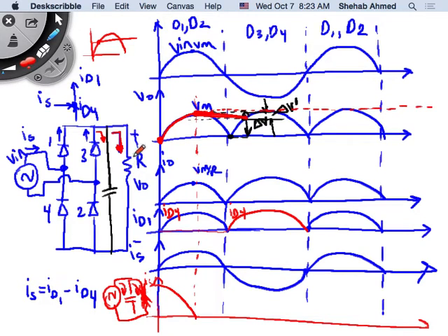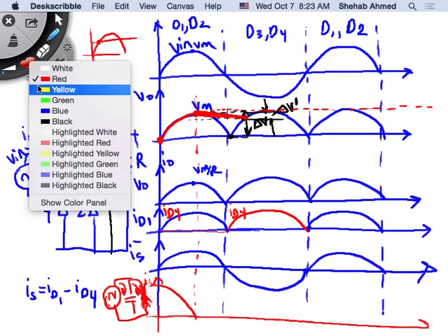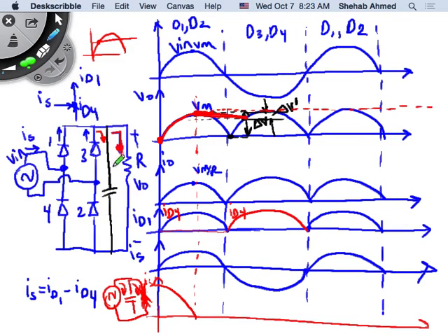So the real case, we will have a resistor connected. If the resistor is connected, what's going to happen? At this point here, we said the supply voltage starts falling. That's fine. And the capacitor voltage will also start falling. Because as soon as you've charged the capacitor to its peak value, this capacitor has a large voltage across it. And this capacitor also has a resistor parallel to it, right? So this capacitor will tend to want to feed the resistor.